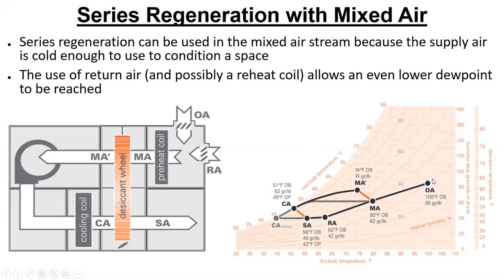This side represents the outside air. It looks like it's about 40, 45% outside and the rest, 55, 60, 65% or so, return air, because this line looks a little bit longer than this line, and this line indicates the fraction of the return air. But it's not too far from 50-50. So anyway, we do our mixing.